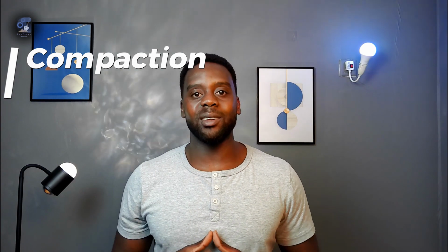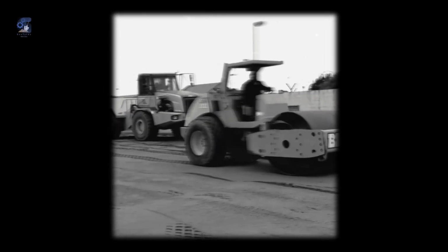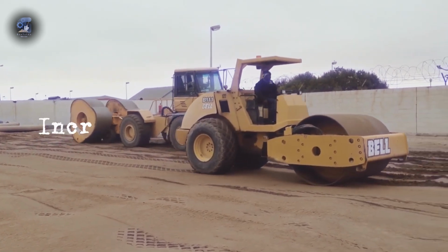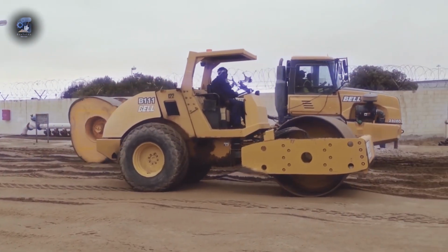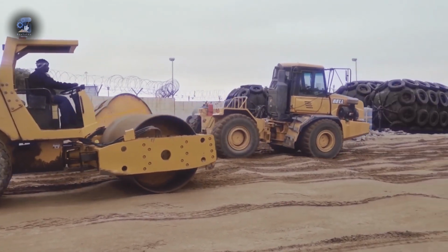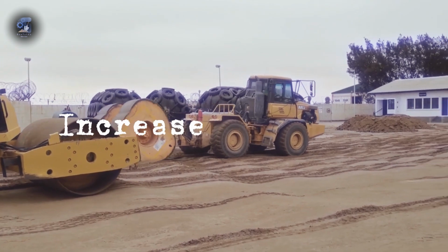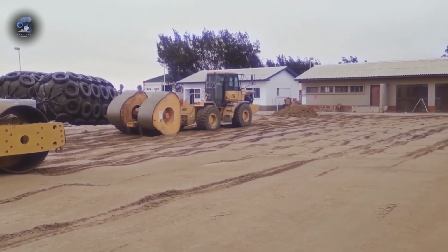This is followed by the compaction characteristics of the borrowed material. Soil compaction is one of the most important geotechnical concerns during the construction of pavements and related fields and embankments. Compaction improves the engineering properties of soils in many ways, including the increased elasticity stiffness, which reduces the short-term deformations during cyclic loading from traffic, decreased compressibility, which reduces the potential for excessive long-term settlement, and increased strength, which increases the bearing capacity and decreases the instability potential.